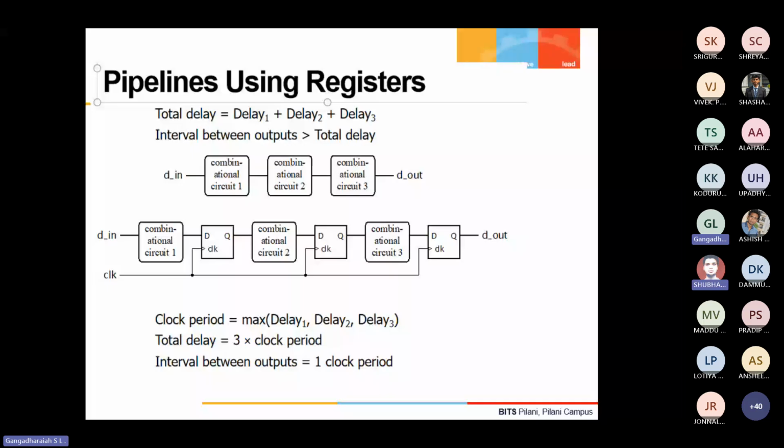Right now I'm facing this issue in my project. I'm a physical design engineer. Right now, meeting timing in STA is close to impossible. We don't have margin. So I have requested the RTL team to add pipelining. Yes, the RTL guy should look into it. Of course, he has to tweak his RTL to some extent so that he will give you a better bandwidth for you to look at it.